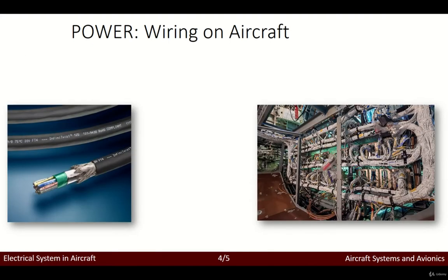Okay, so again, the most generally used conductors are copper and aluminium, okay? Each has characteristics that make its use advantageous under certain circumstances. Also each has certain disadvantages. So copper has a higher conductivity, for instance, is more ductile, has relatively high tensile strength, and can be easily soldered, okay? Copper is also more expensive and heavier than aluminium. Although aluminium has only 60% of the conductivity of copper, it is used extensively.